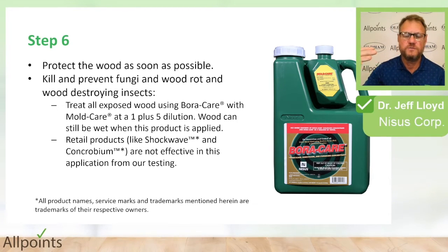As soon as you've removed the sheetrock and removed the insulation, you can do an application with a product like Boracare with Mold Care. The wood does not have to be dry. Do not wait for the wood to dry before you do the application. It's over that drying time that the wood will start to grow surface fungi and really start to look bad. So the sooner you do this application, the better. The application is designed to kill and prevent fungi. So any fungal spores on the surface of the wood, any small amount of growth that you've already got there, the treatment will kill that growth.